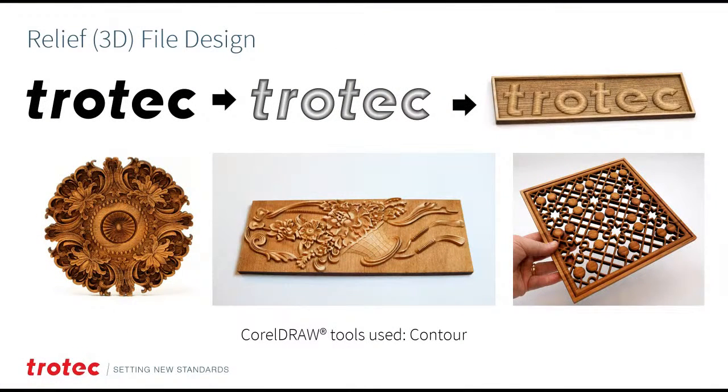All right, another very popular one in CorelDRAW is how to create relief designs. Relief designs, or 3D relief designs, are the process of varying the shades of grayscale on your graphic, so when the laser engraves it, you get that same gradient, three-dimensional pop-out look onto the material.